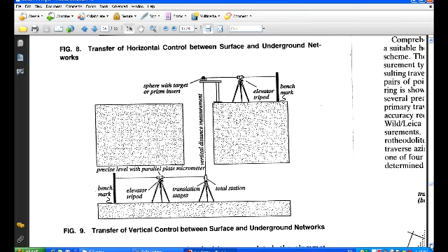So that would get us from the center of the total station over to the benchmark down below. So you have two backsight minus foresights and the distance between the center of the sphere and the center of the total station, and combining these together would end up providing us with an elevation of the benchmark down below.